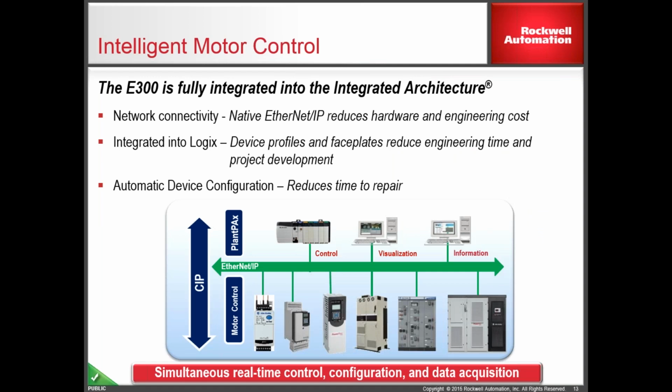So when we look at the E300, one of the nice features and one of the reasons that we consider it a smart device is because we can easily integrate it into a Logix architecture, similar to some of our drives or soft starter products. With that, we have obviously the Ethernet connectivity that Andy mentioned. We have the dual port Ethernet COM module on the front. Within Logix, we've got an add-on profile for it, and I'll actually go through a demo of that.